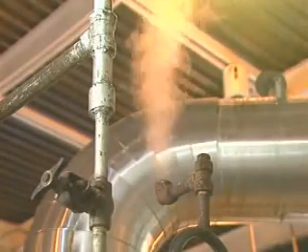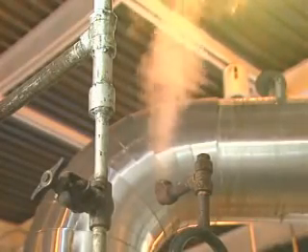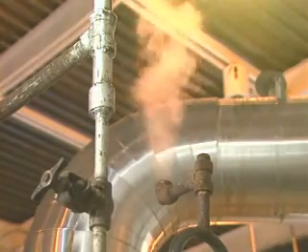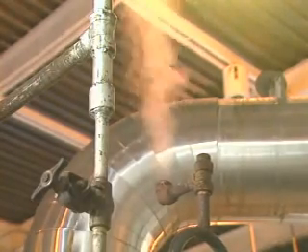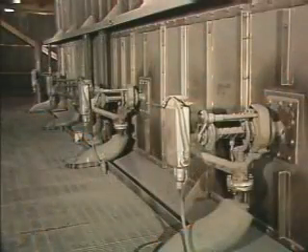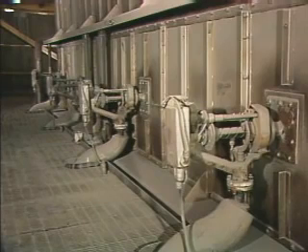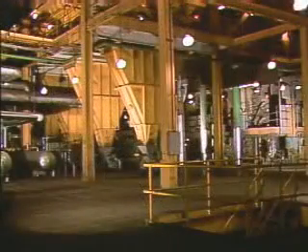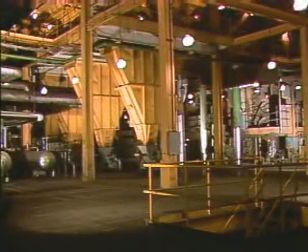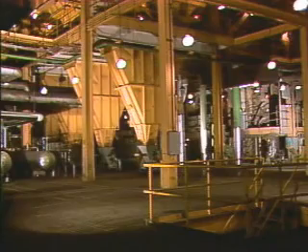Proper boiler operation requires the flow of feed water into the boiler to equal the flow of steam leaving the boiler. If too much feed water flows into the boiler, moisture could eventually build up and carry over into the main steam system. On the other hand, if there's not enough feed water flow to meet the demands of the boiler, it could boil dry.